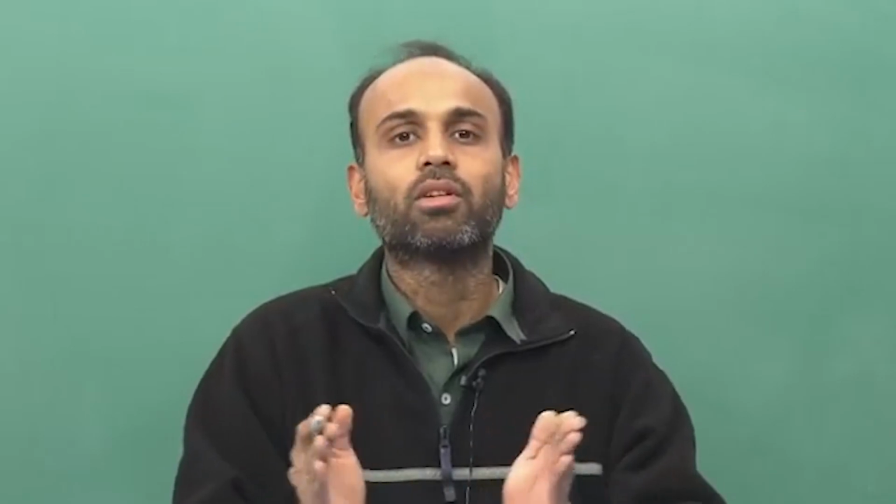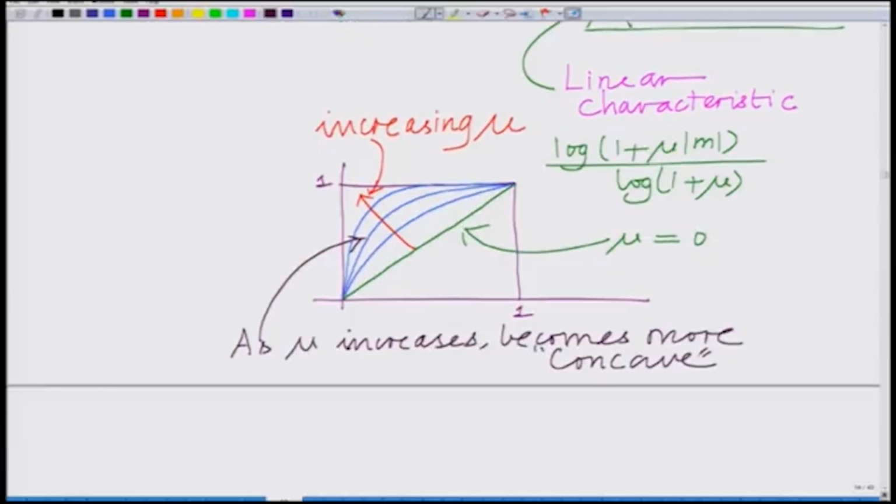So, the resolution, that is the number of bits or the number of intervals, for the smaller amplitude or the finer amplitudes improves progressively as mu increases, and the resolution or the accuracy of the larger amplitude region progressively shrinks as mu increases. Okay. So, that is the mu law compressor.